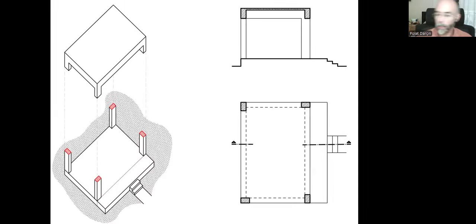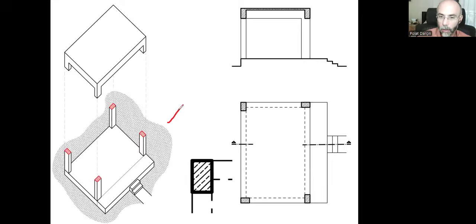The first thing is to emphasize the cut surfaces of the plan and the section. And here, as you can see, I'm using thin lines, but one 45-degree inclined line, a continuous one, a little gap, and then I do a dashed line in the same shape, in the same direction, and one more continuous line, and then one more dashed line, and it goes like that.